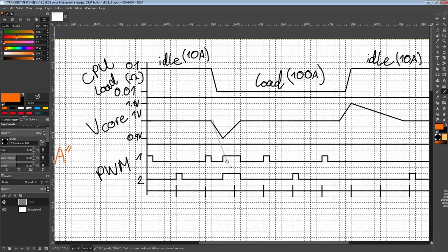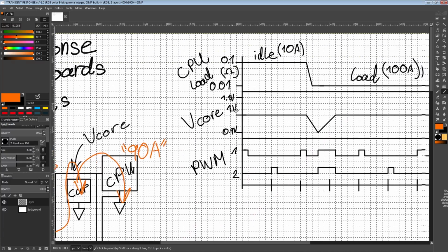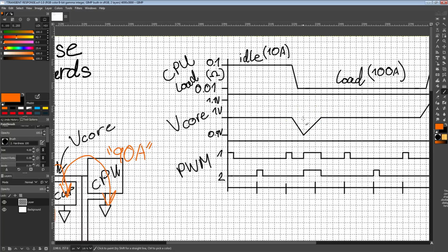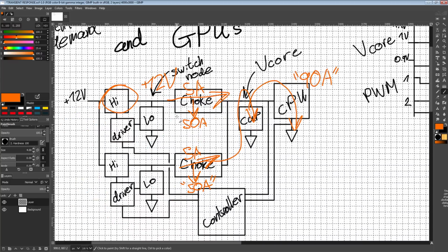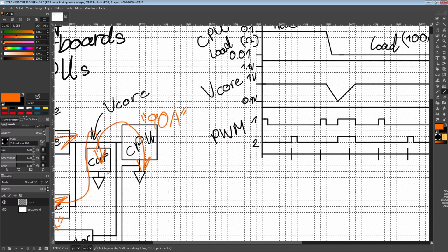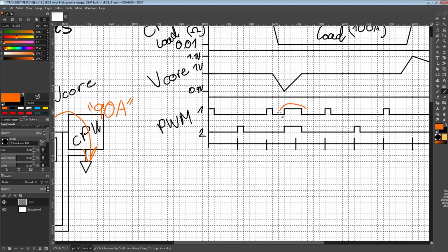A bad transient response is potentially a very large deviation, and then it might take forever to recover as well. So that's a load insertion transient, and that's your undershoot, and it's entirely caused by the fact that you just can't force the inductors to provide a bunch of current until you turn on the high side MOSFETs. And even if you have the high side MOSFET turned on, you might have to do something like a PWM pulse extension.